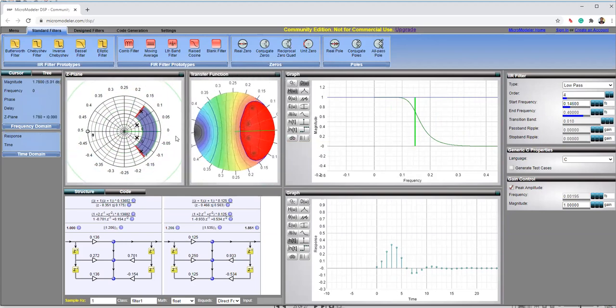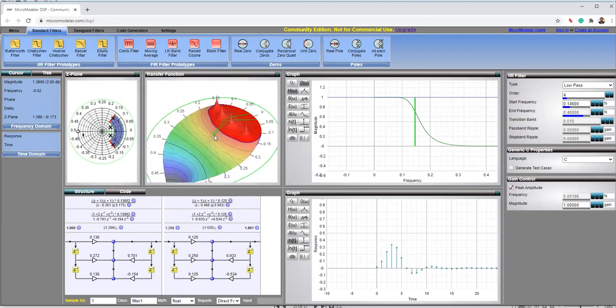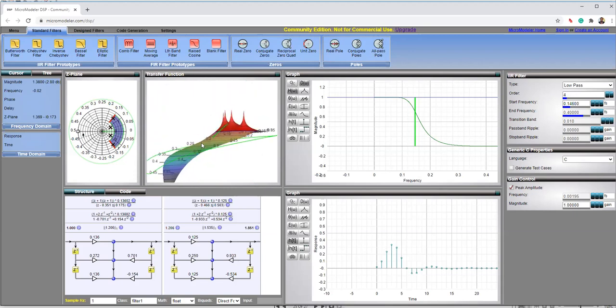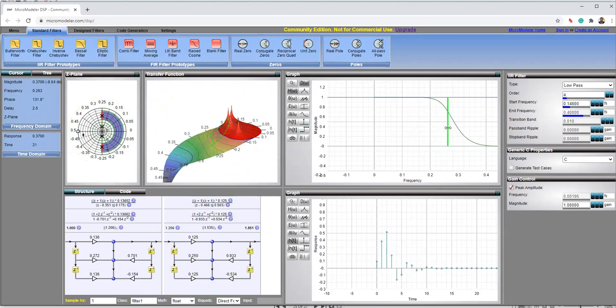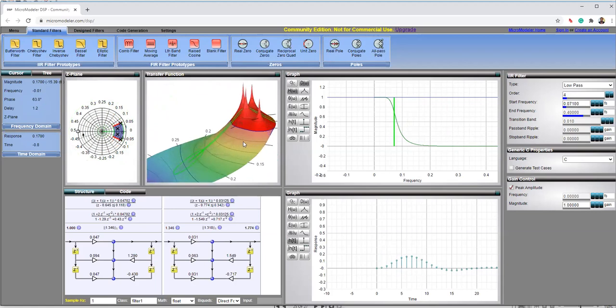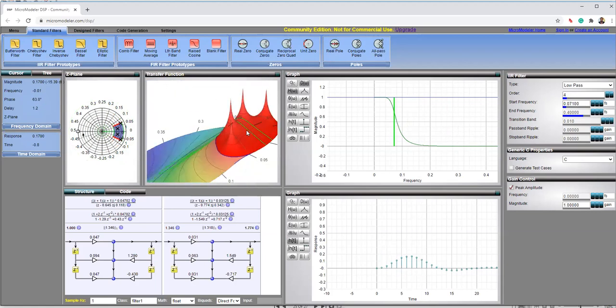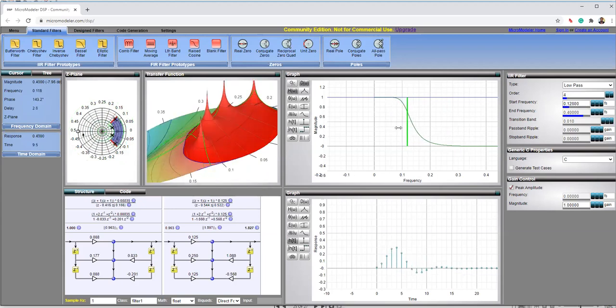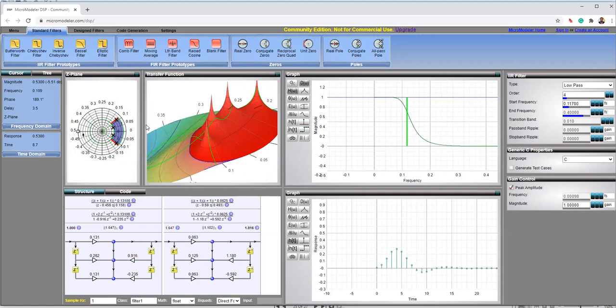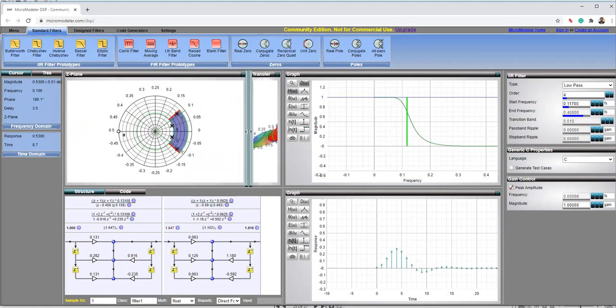And if you want to see the transfer function, it is very convenient. You'll see the zero location. So this is a zero and the poles are there. If I change the pole locations, the pole locations will definitely change. You can magnify and see the pole locations, the time domain response, and the circuit as well. Let's say we'll have very complex circuits. So this is a very good tool to play with, isn't it? Yes, sir.